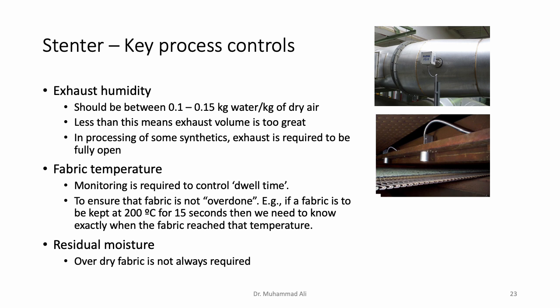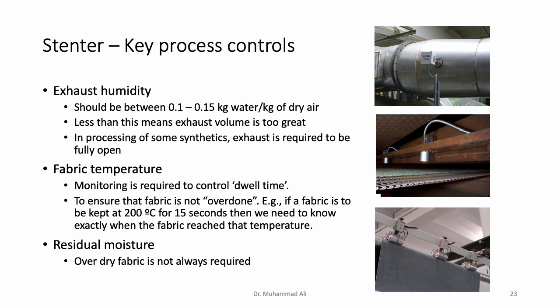And the third aspect is the residual moisture. That is the moisture in the fabric which is coming out of the treatment chambers. Now, we want the fabric to be dry when it comes out of the treatment chambers, but if it's bone dry, then that might not be required actually. So if we have a system, we can have sensors that are installed at the exit of the treatment chambers.